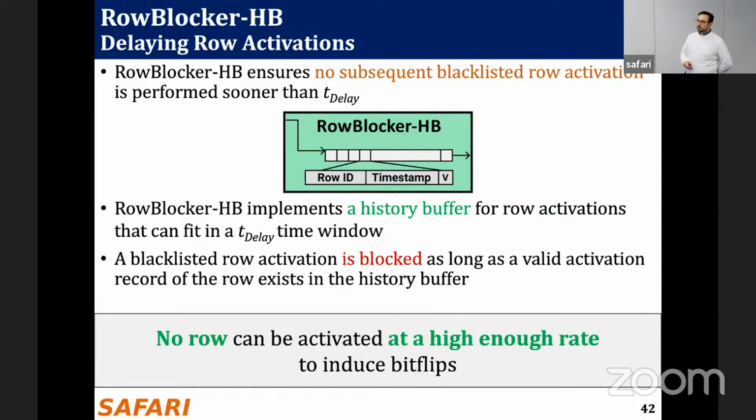What if you use just one counting Bloom filter with the addition of some counter bits that mark a row as already blacklisted, and you don't reset it at the epoch period, using something like shift registers? The counters are shared across all rows, right? Yes. We do not reset based on a particular row being blacklisted or not.